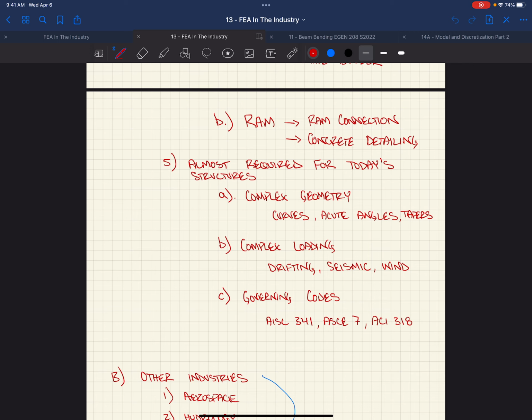Yeah. So then that's how that energy dissipation works, it's like a fuse, right? You're gonna push, and then the first thing that reaches its limit better be those braces. Or better be that plastic hinge in your moment frame, right? In your beam. It better not be in the column, it better be in the beam, right? Strong column, weak beam, sort of thing. Right? Ordinary, just stay ordinary.